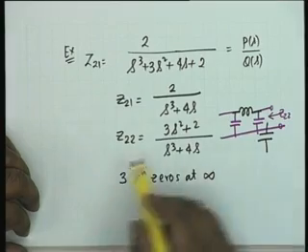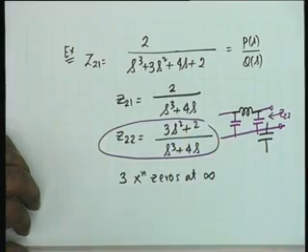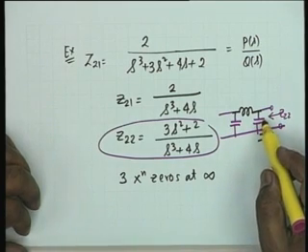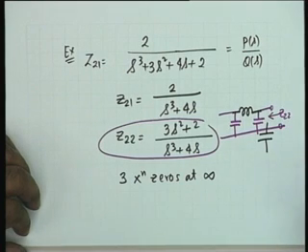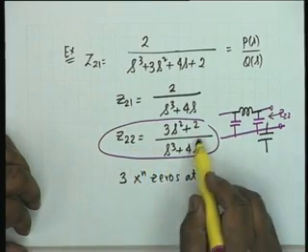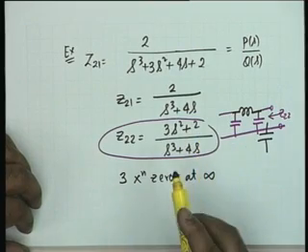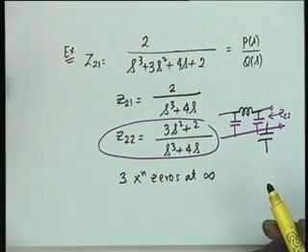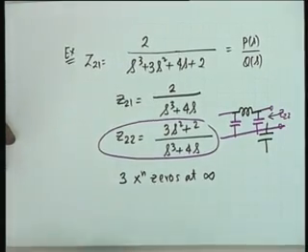What I was saying is, all that you have to do now is to realize this function in this particular form, and you see that this is a Cauer 1 structure, and therefore it can be mechanized by continued fraction expansion starting with the highest powers. Now, you cannot start continued fraction expansion of Z22 because Z22 does not have a pole at infinity, and therefore you have to start continued fraction expansion of 1 by Z22.